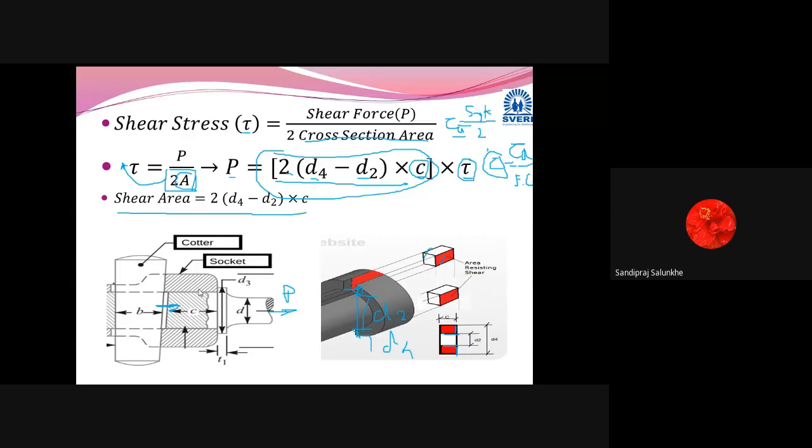Now, if we are going to make this socket and spigot strong to sustain that P, now we'll concentrate on this pin, because this pin is the locker one, because this is going to lock these two parts, that is socket and spigot. Okay, so this pin is also undergoing various stresses. Now you can just list out which stresses will be induced in that quarter pin.